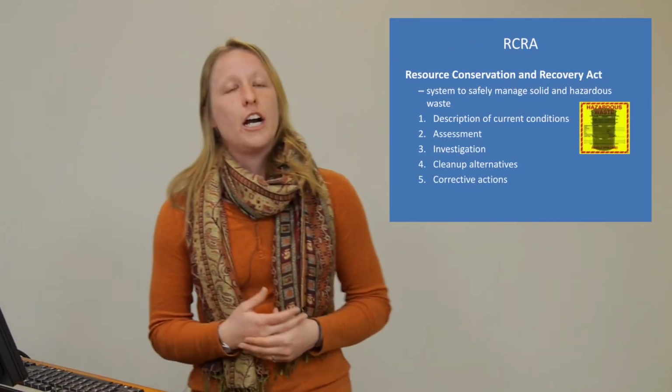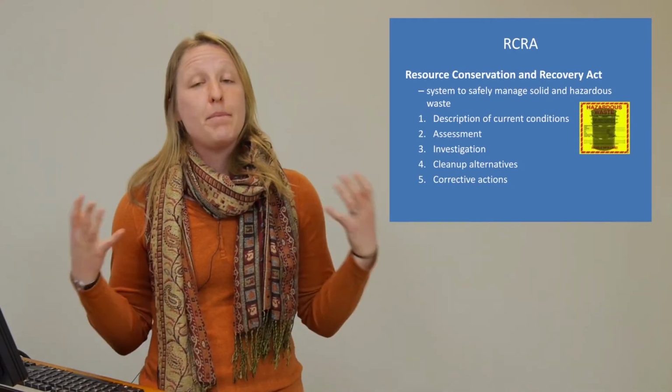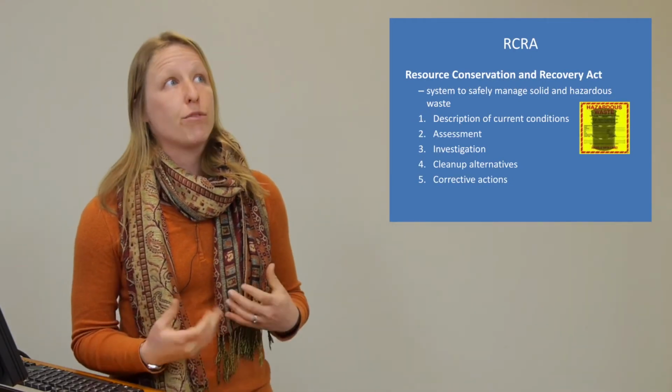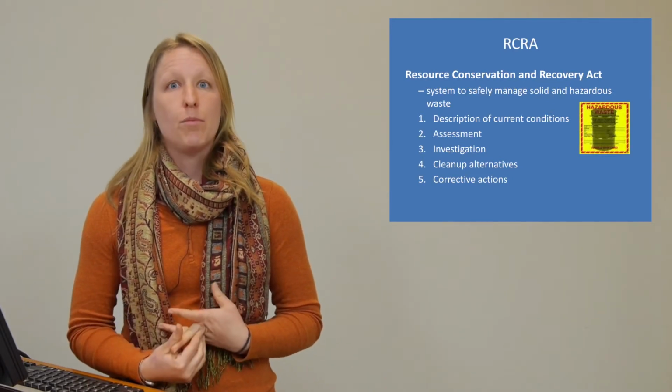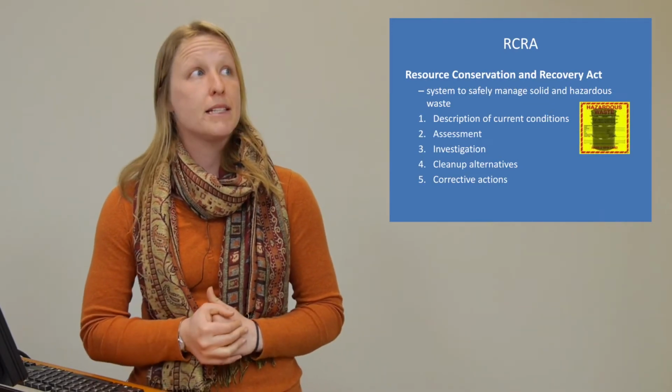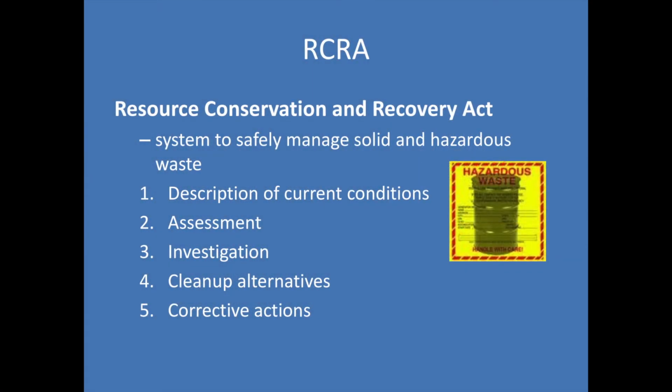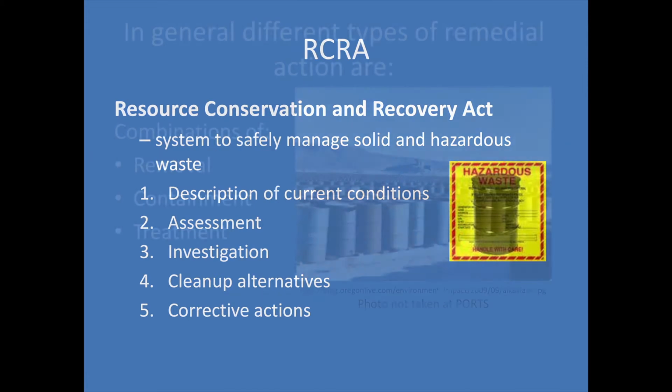Cleanup decisions are made based on RCRA, or the Resource Conservation and Recovery Act, through consent decrees with the state and federal government. What this includes is an assessment of the site and a description of current conditions, and from that, an investigation to figure out the removal, containment, and treatment options in terms of our cleanup alternatives. And groundwater modeling has a central role to this at ports.